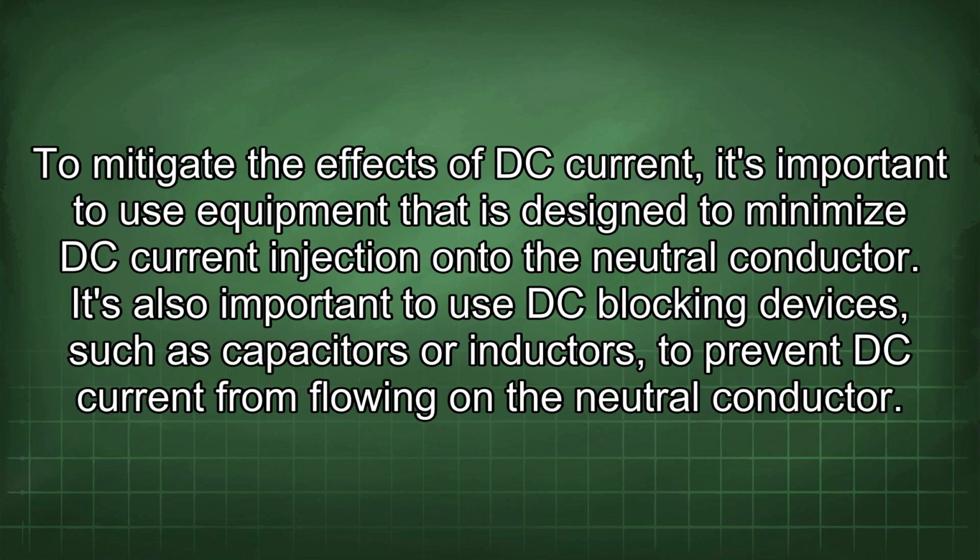To mitigate the effects of DC current, it's important to use equipment that is designed to minimize DC current injection onto the neutral conductor. It's also important to use DC blocking devices, such as capacitors or inductors, to prevent DC current from flowing on the neutral conductor.